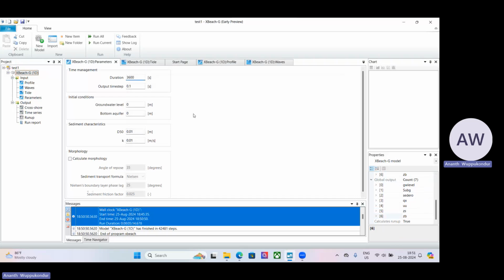So in this present simulation, we have not used any bed elevation calculations. So if you see, morphology corresponds to the bed sediment transport, and we have not turned on sediment transport in this simulation. So that is why, even though the model has output some ZB, we would not see the bed to be changing with time. So the bed would be constant because we have not turned on any sediment transport.